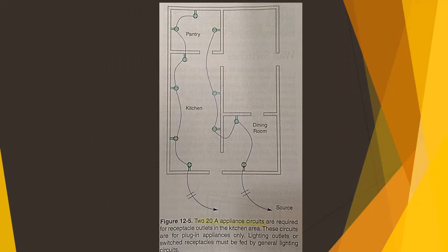Small appliances. There must be a minimum of two 20 ampere circuits dedicated to receptacles for small appliances. This circuit load can be included with the general lighting load as stated in section 220.52(A). These receptacles are located on walls and floors and are used primarily for kitchen appliances.